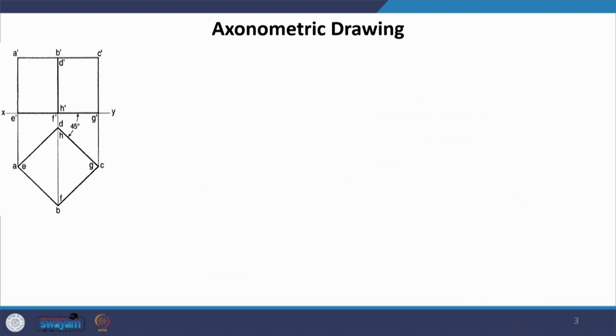This is a cube which is now tilted. Now, we will have to see how we start drawing it. So, I will make a reference rectangle here, which is enclosing the base of this cube. Now, this cube is inclined. So, this is what we are going to make first. Directly we could draw, but then you have to get the angles.